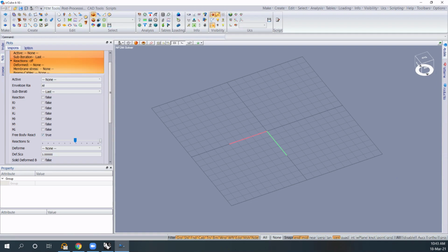The C values govern the shape and the level of pre-stress in the membrane. Now, in the initial stage, we are searching for a shape. How do we shape the membrane? We shape the membrane by changing the pre-stress of the membrane. Clearly, we have also the boundary edges. In this case, everything was fixed, but generally, we have also cable boundary edges, so we can change the shape of the cable boundary. But in the beginning, we want to find a shape that fits our design. How do we do this? We do this by changing the level of pre-tension in the membrane.